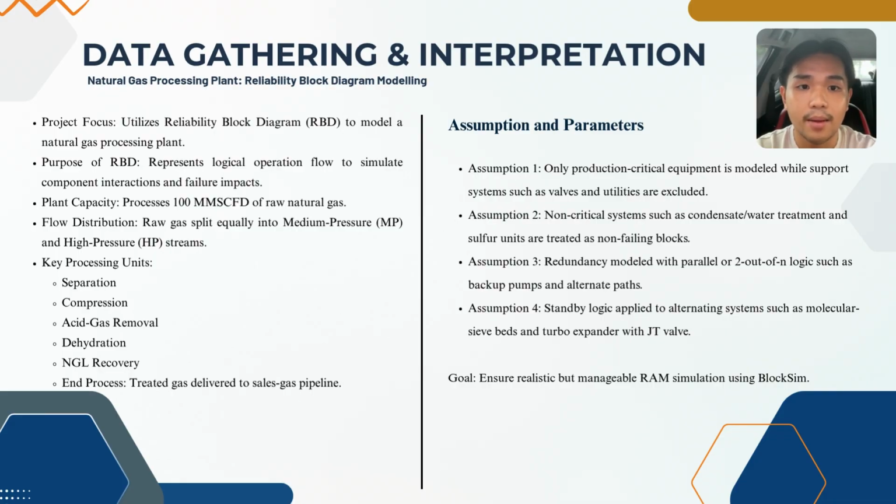Finally, we applied standby logic to systems that alternate between active and standby modes, such as the molecular sieve beds in the dehydration units and the turbo expander system, which is backed up by a JT valve. This assumption helped us to create a model that is both technically valid and suitable for RAM analysis using BlockSim.